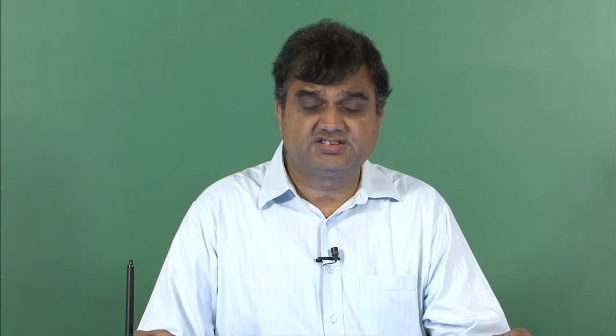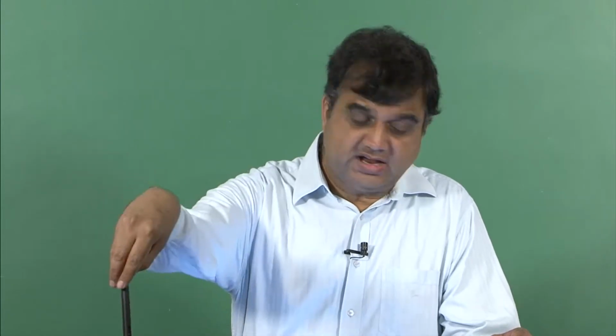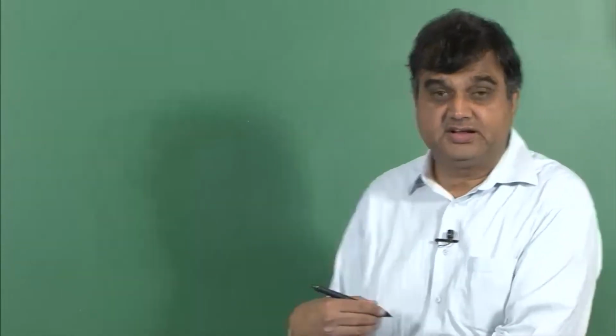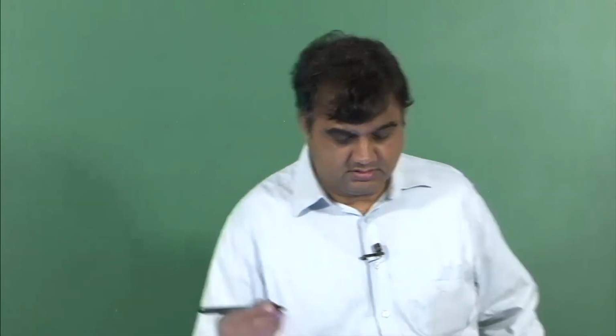Today is the fourth day of the ongoing week, which is the third week of the course, and what we plan to do today is develop relations at the plate level using classical lamination theory between force resultants, moment resultants, and mid-plane strains and curvatures. That is the objective of today's class, and for that, first I will lay down the convention for numbering the layers and also identifying the z coordinates of a laminated composite.